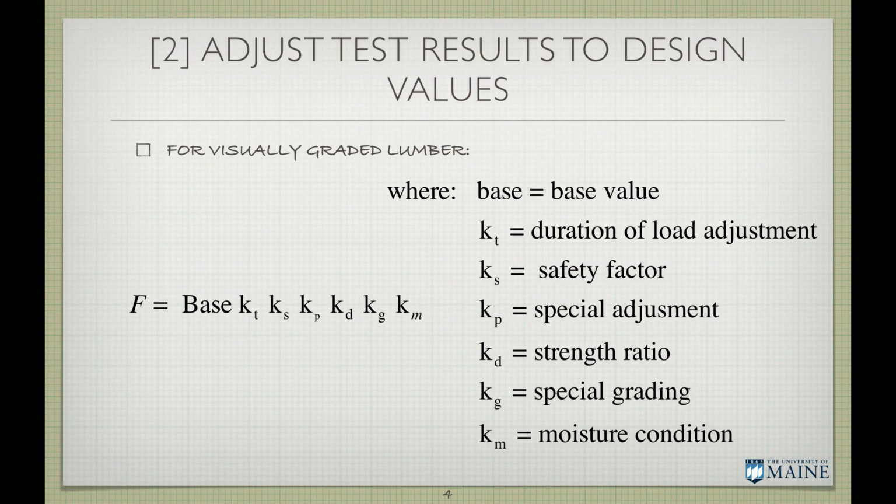So here's what these adjustment factors are. The base value, we'll define what that means later. K sub t stands for duration of load adjustment. Duration of load refers to time. So that's going to introduce us to this concept of viscoelasticity, creep rupture, and those kinds of things.